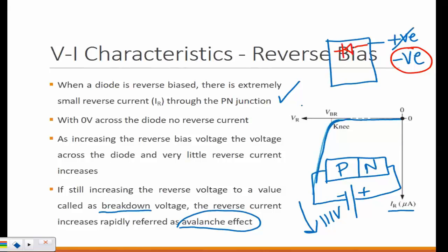So if you put a positive voltage, if it's well over 0.7, it will simply allow it, whatever the current is. But mistakenly, if you switch it, let's say you don't know how to connect a battery, if you don't look at the polarities, or if you don't look at the manufacturer data sheet, then there may be a possibility where even momentarily you apply negative voltage, you may cause the device to be permanently damaged. So most of the ICs will be protected like this internally.